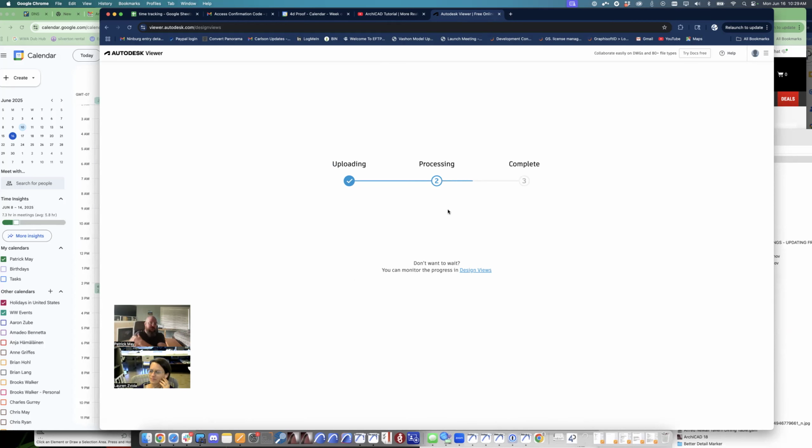No, definitely. You won't have the time to. If you've got five projects to get cleaned up in the next 3 days, I would say go through this process for plans, sections, and elevations for each project first, because at least then you're getting them the very basics of the design. And get them DWGs and PDFs. Never save just DWGs because there might be things where, oh, these markers weren't referenced.